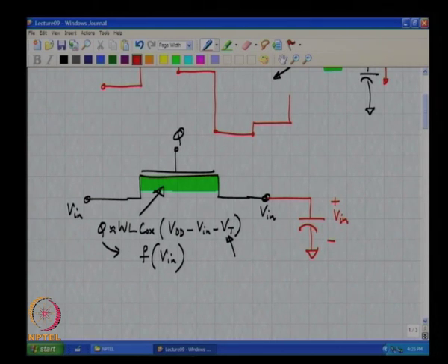Then we turned the switch off, and some fraction which we as yet do not know of the channel charge has gone and lodged itself on the capacitor, correct. So, if this is C, that amount of channel charge will cause a voltage jump of value. The injected charge, so this is called charge injection.